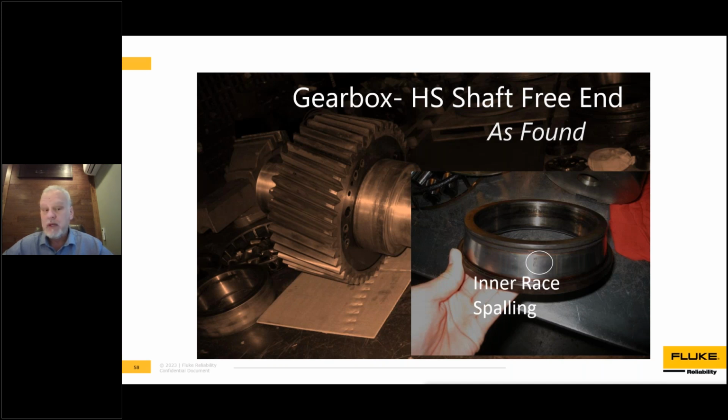We've had this issue even with some of our own analysts, because at the Technical Associates Vibration Institute, I think we have historically taught that these tools are only useful in very early stage bearing detection. Every one of the examples I gave you was late stage bearing detection.